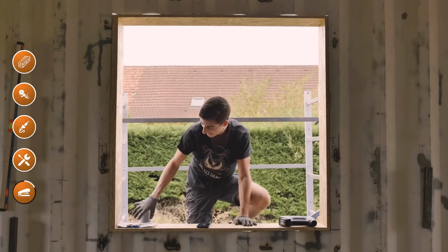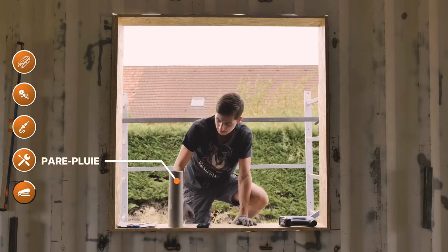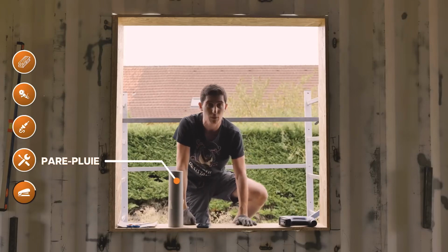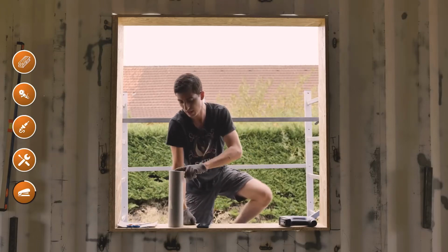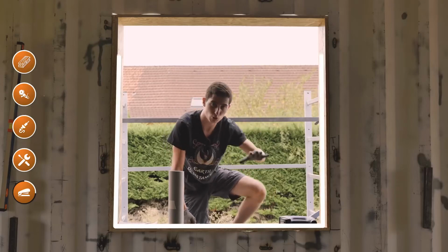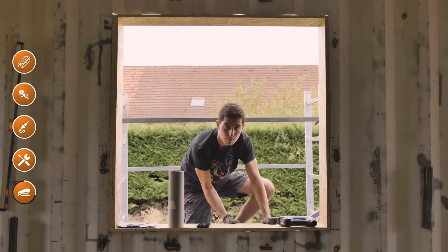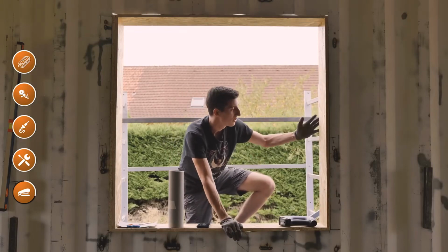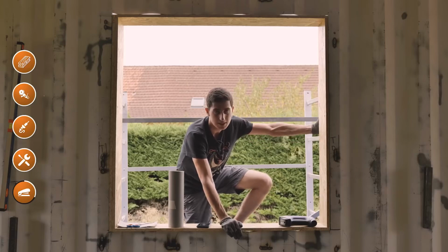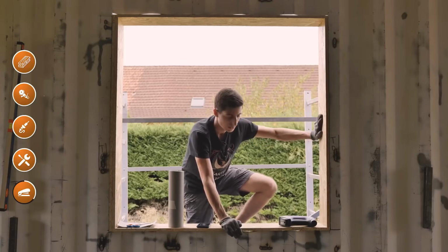Now what we have to do is install a rain barrier to protect my oriented strand board, and we're going to staple this rain barrier. So I already cut a 5-meter long roll to go all the way around the window and 30 centimeters thick so that it's on the oriented strand board and I can bring it back a little underneath. Then the rain barrier for my cladding, the one that will be between my cladding and my insulation, will go on top like this, and that's it.